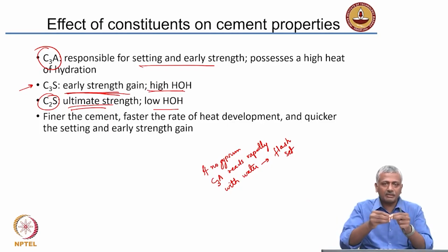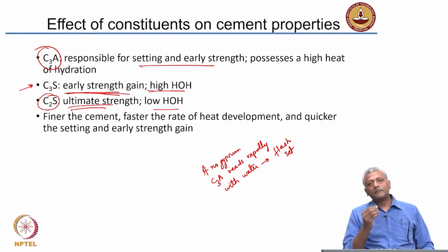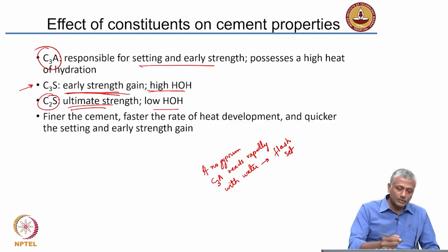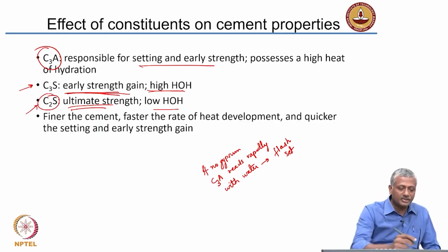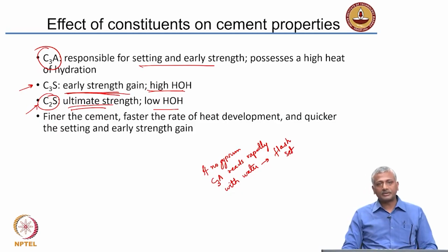The heat that is getting generated inside does not dissipate out quite easily. So you get build-up of thermal stresses, and that is not good for the concrete because it will lead to cracking. Okay. So because of that, in such cases, we would like to use a cement that produces less heat, right? So in those cases, we may want to go for cement that is rich in C2S or adopt alternative strategies, as I'll talk about later.